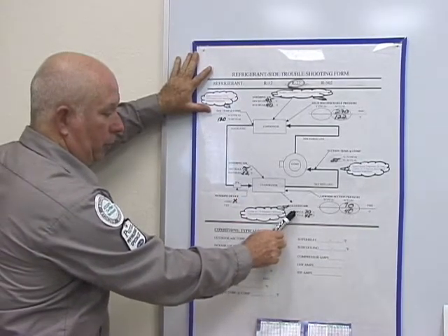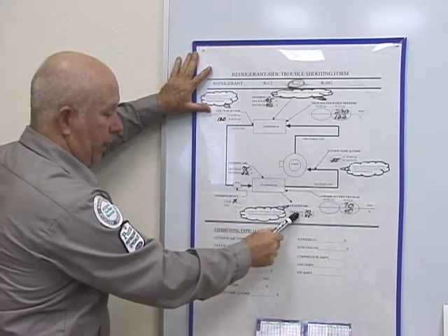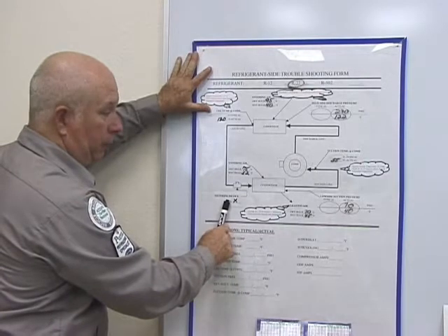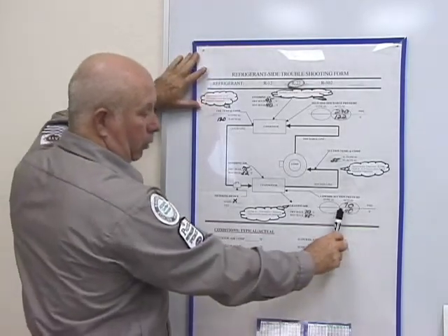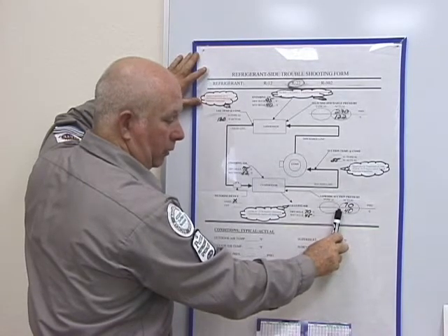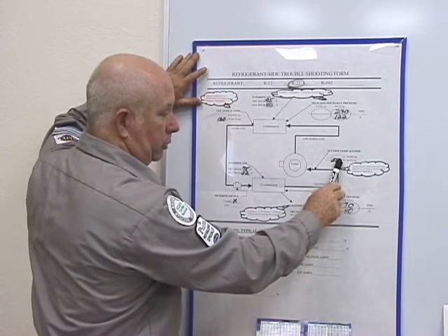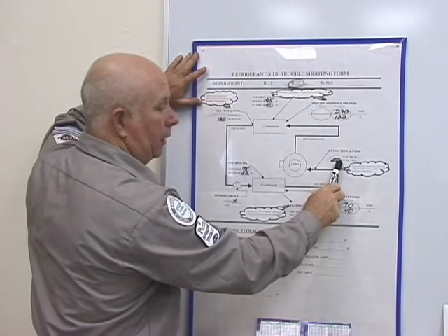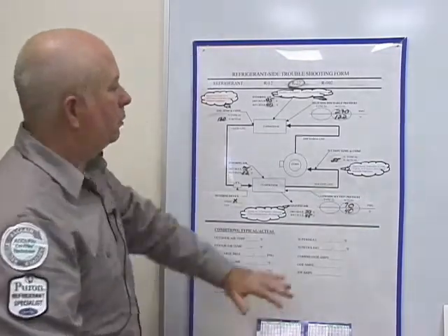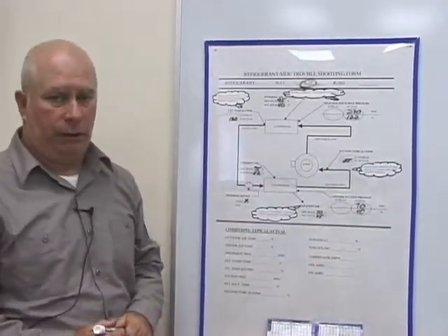Dry bulb, wet bulb leaving air or supply air. This is your return air, supply air. We know we got a fixed metering device. We know our low side suction pressure is 70 with our saturation temperature being 40. And we know that the suction temperature at compressor is 55 degrees. So we know, and it's all in the actual, so we know we have it all taken care of.